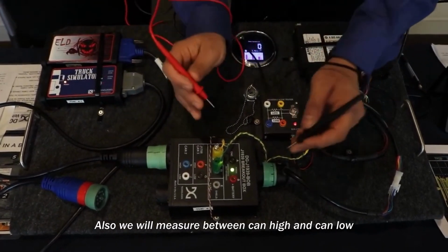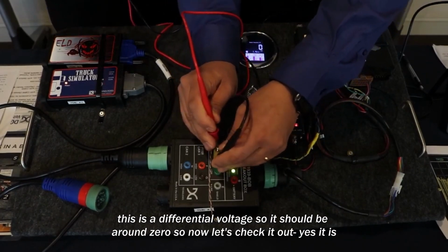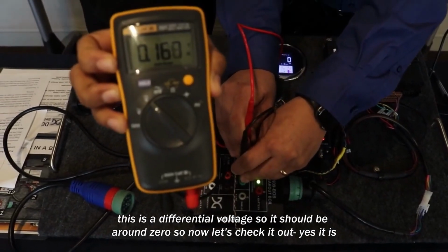Also, we will measure between CAN high and CAN low. This is a differential voltage, so it should be around 0. So now let's check it out. Yes, it is.